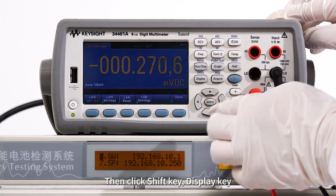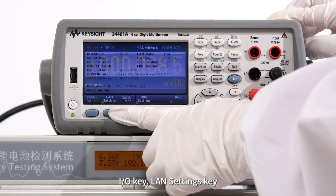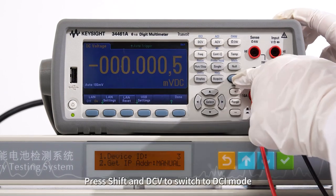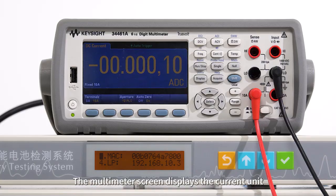Then click Shift key, Display key, I/O key, LAN settings key. You can view the multimeter IP address. Press Shift and DCV to switch to DCI mode. The multimeter screen displays the current unit.